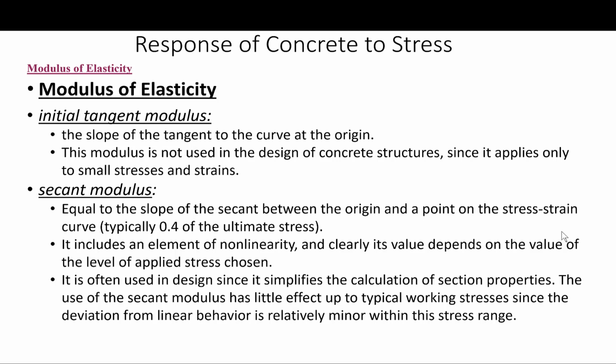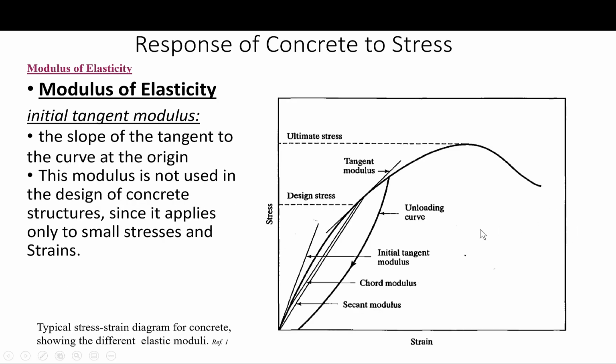This secant modulus includes an element of non-linearity, and clearly its value depends on the level of the applied stress chosen. Okay, and again, another limitation. You see, again, we said the slope between the origin and a point here, all right?